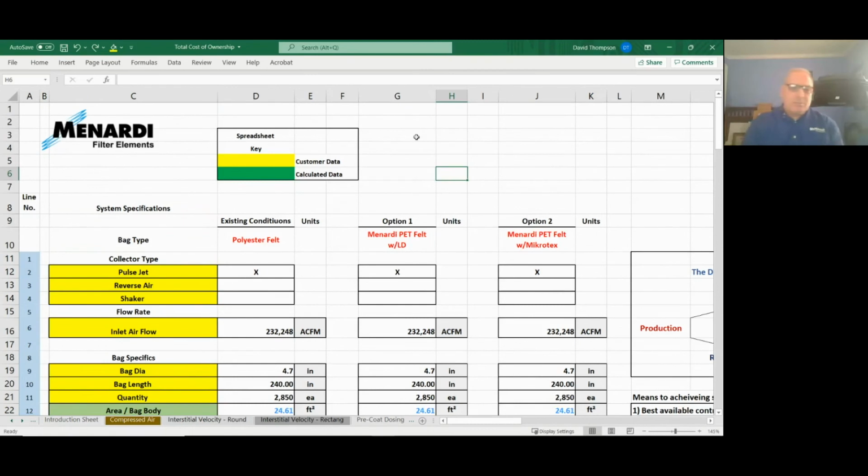So you go back to your original design data. Obviously, plants like large baghouses get built over years. It's designed in year one, and it's actually fabricated and put into place in year three. Their operating conditions may have changed, or their demands from the plant may have changed. So you look at what the design parameters, or original design criteria, are, and then you look at what the actual is. We're really concerned about the actual.